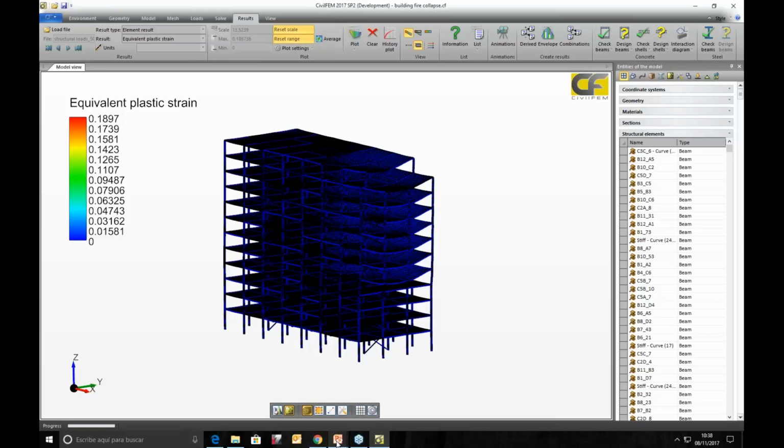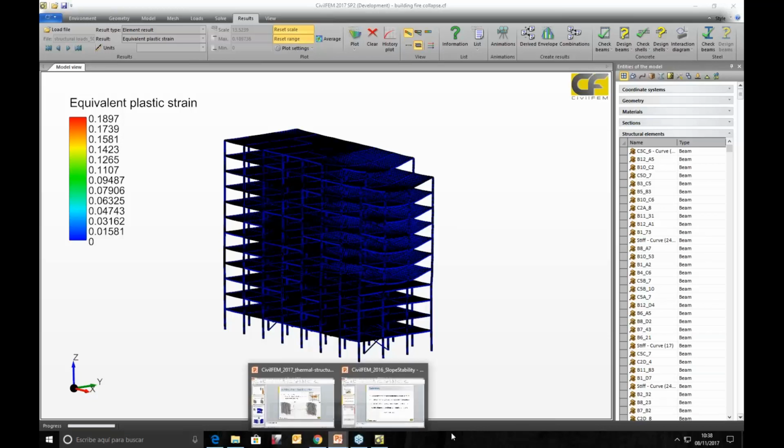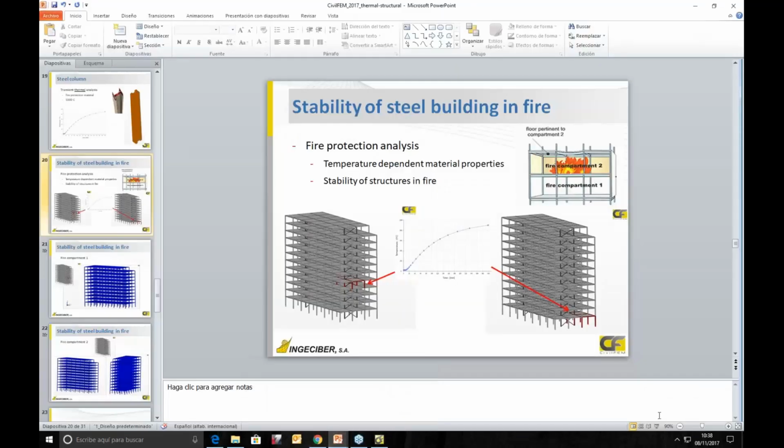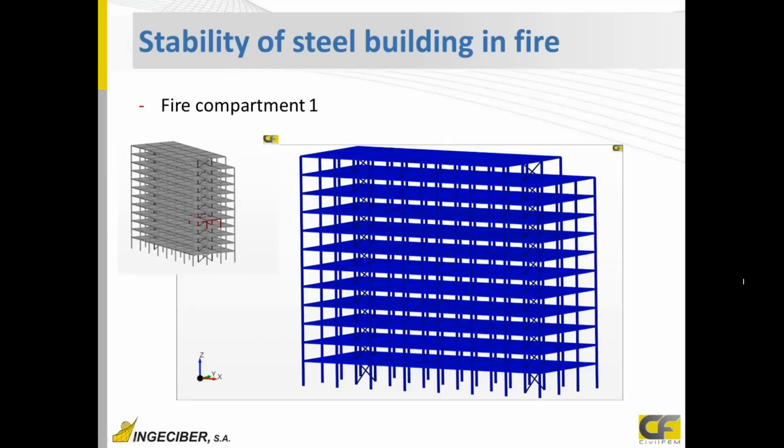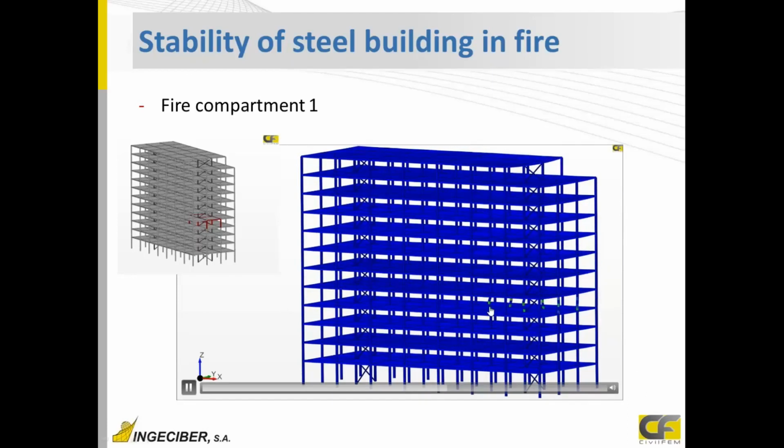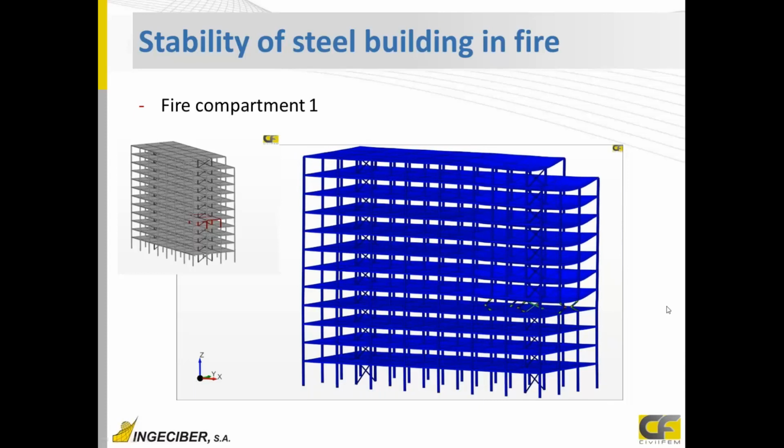And just checking the slides here, we can see results in both. The first applying only in this zone. Here we can see the video during the time that yielding starts here and buckling is happening in those zones due to fire.